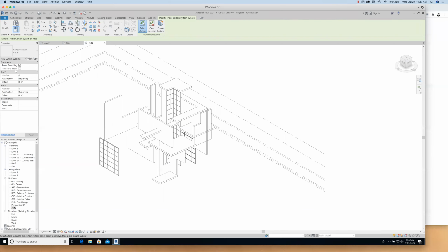You know, there are other ways of thinking about this. For instance, if you're trying to fit a 4 foot by 4 foot grid in something that isn't exactly 4 feet in height or a multiple of 4 feet in height, you can think about where that pattern stops and ends. So do you want the strange irregularly shaped pieces to be at the very top, or do you want the grid to be centered and things like that? You can talk about justification and center things up, or actually have it justified to one edge or the bottom or whatever. Okay. So there are more parameters, let's say I wanted to select this and change some of these things, but I'm just going to leave it as is, okay?